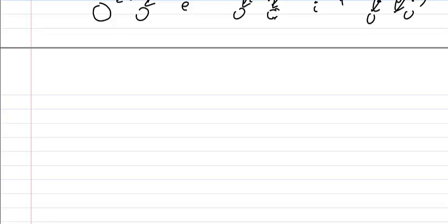In this particular case, everything has gone to 0. All that we're left with is 0 equals the summation over all exit streams of m dot e h e minus the summation over all inlet streams of m dot i h i. So now let's go ahead and plug in the appropriate numbers.